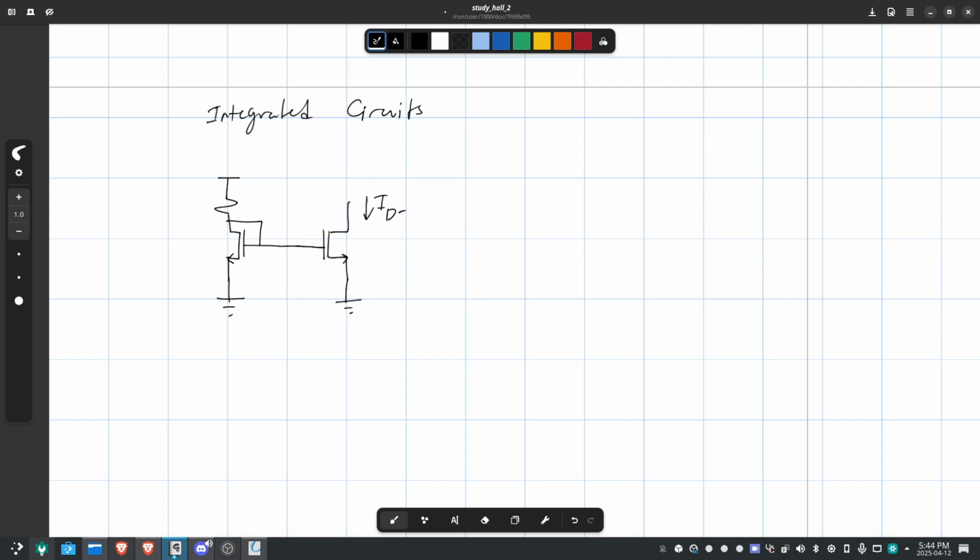So we're going to call this ID2. This is M2. This is M1. We have ID1. We can use this to regulate current, and it can be used as a current amplifier. Under here we write the current ratio, so say ID1, ID2. In this example, you could see 1 to 1. That means whatever current is flowing in this direction is going to be flowing in that direction. Sometimes you will not be given that ratio and you'll be asked to figure it out.